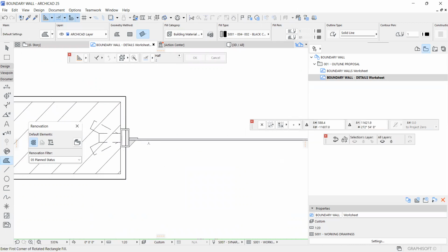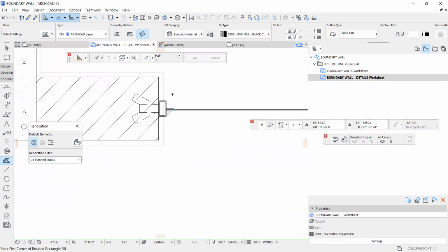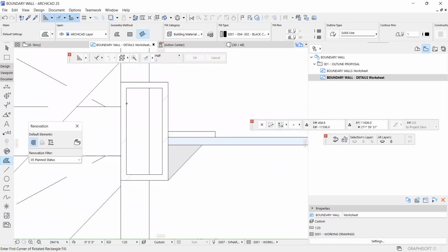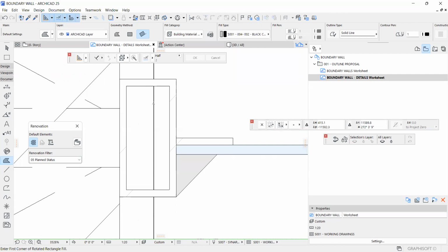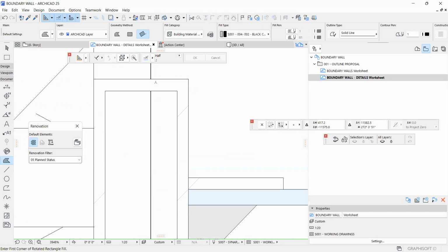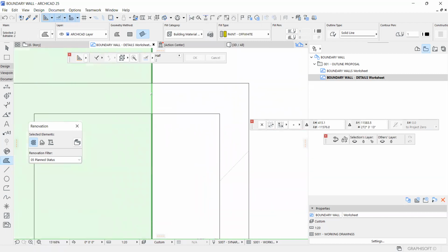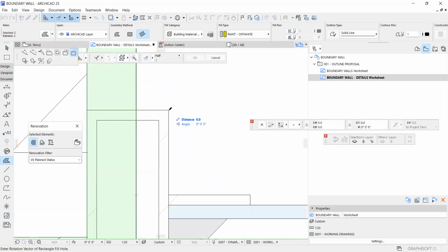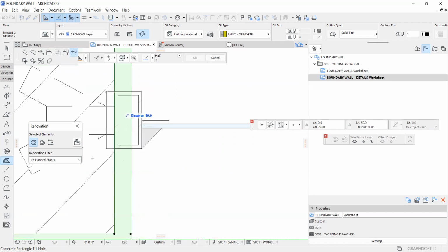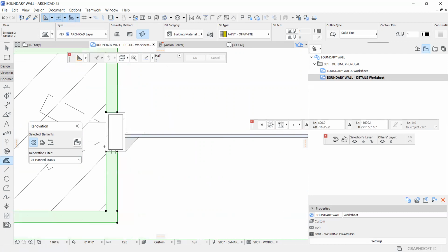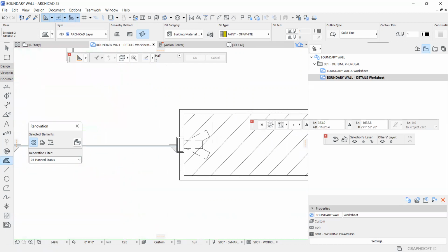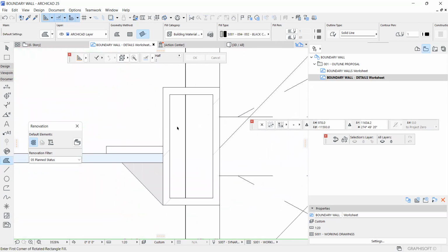So as you can see, we are done with that. The only thing is our plaster and our paint. Rule of thumb, you fix the window before the plaster and paint, so that one should not be seen in any way. So let's chop off that portion. Normally fix the window first and then come and do the finish properly. The same case applies to this.